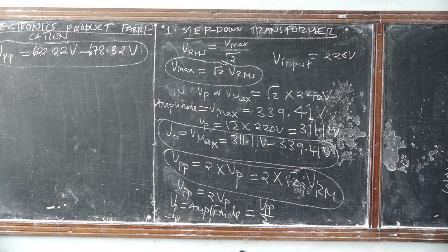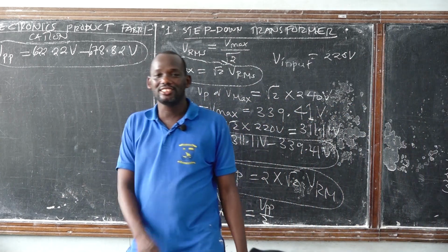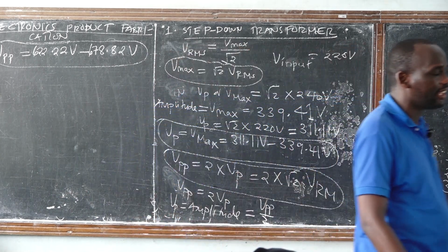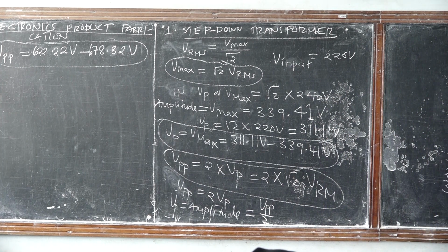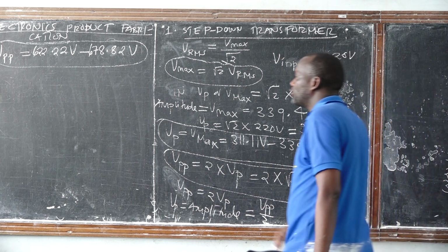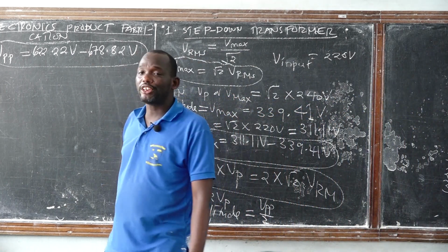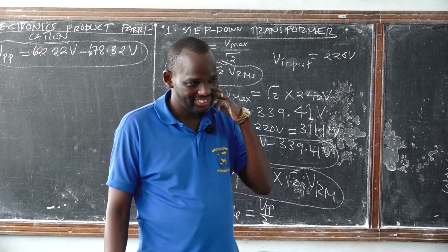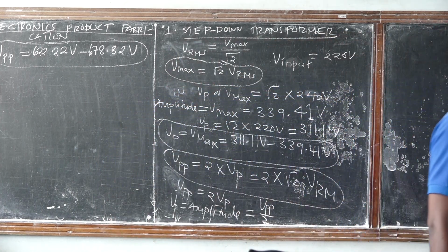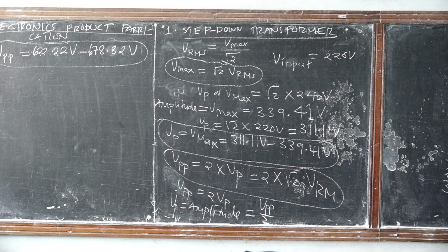Have you ever thought why in a signal generator there is no chance to feed the peak-to-peak voltage or the root mean square voltage? The reason is that the signal generator gives you signals of different waveforms. Not all the waveforms are sinusoidal, and not all are cosinusoidal. Some of the waveforms are pulses, and the pulse does not have a root mean square voltage. The triangular wave does not have a maximum or root mean square voltage either. That's the reason.